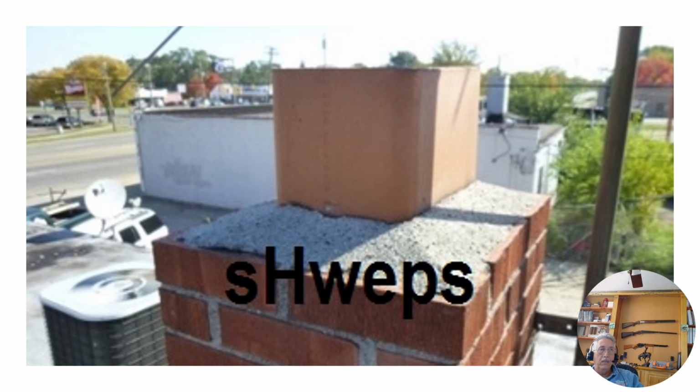And the data plate there, it's called the data plate. Still on H, there's a chimney which the furnace was vented into. There's no liner, no rain cap, no spark arrestor. That's a defect for the report.